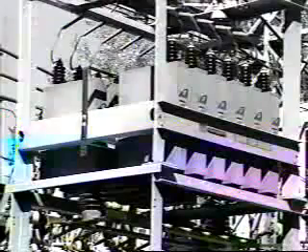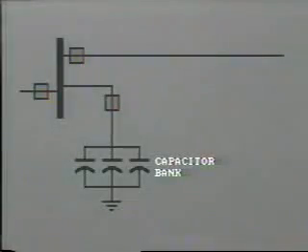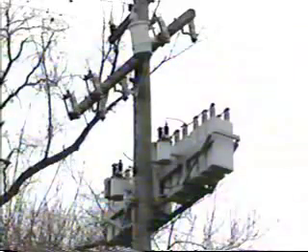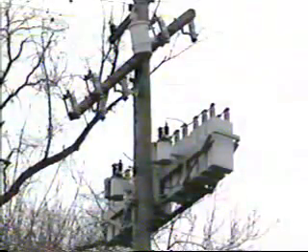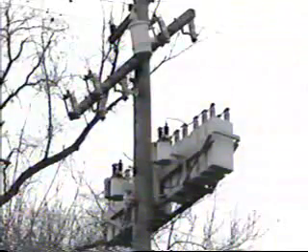While we're speaking of shunt reactors, we can also think of shunt capacitors. As you know, these capacitor banks are connected between line and ground or bus and ground in order to raise the voltage at that location by supplying VARs to the system. The capacitors actually compensate for the series inductance in the line and are commonly applied throughout the distribution system.